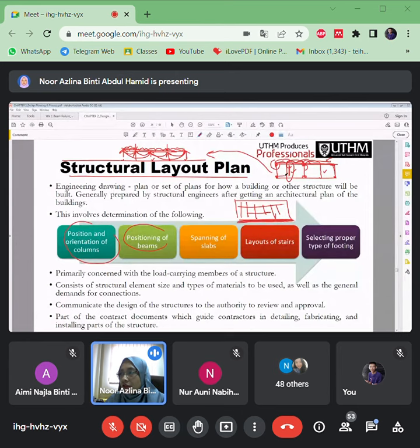Let's say it mentioned these beams, all these corners here, semua corner ni ada brick wall. So nanti dalam you punya structural layout, that means semua ni adalah beam. You kena provide beam. You tak payah lukis brick tu. You kena lukis beam. You just draw for your structure. So that means this should be a beam. Apa size dia? Okay. Then this will be the beams line, according to the brick wall information from the architect here.